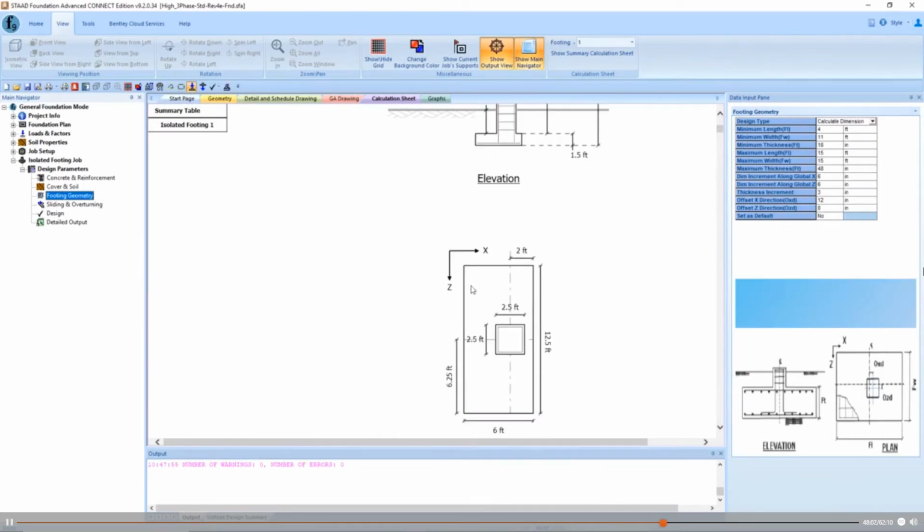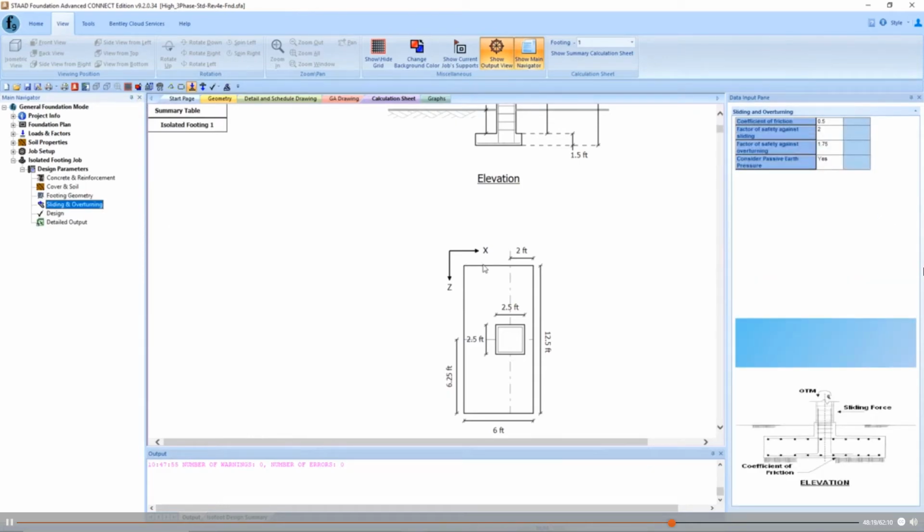Now, why did I do that? Well, I know I'm going to have another foundation on the other side, so there's going to be that lateral support in there anyway, and I know that those foundations will be working together. So this is something that I can take advantage of.